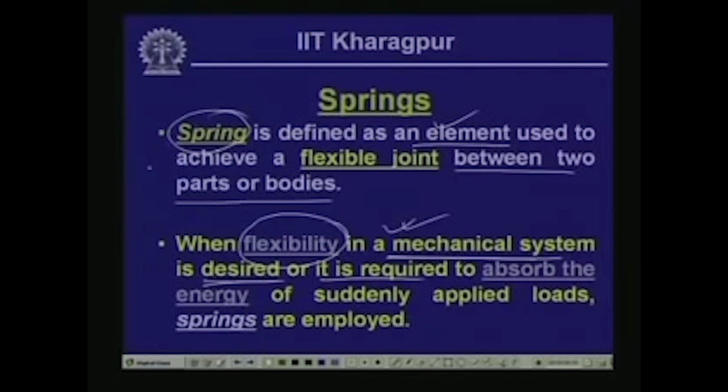spring. Or also if we like to absorb some energy. In many places, structural members or mechanical systems are subjected to sudden loads. If these kinds of sudden loads act on structural members, the member may undergo large deformation, and thereby there could be stresses which go beyond the yield value of the material.